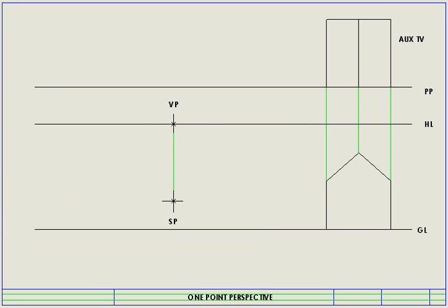We are now going to start connecting our stationary point to all the points that are not touching the actual picture plane. Reason being that I want to force each one of the points that are not touching the picture plane onto the actual picture plane, and therefore create points on the picture plane. Okay, I'm going to go ahead and make my marks on the picture plane.